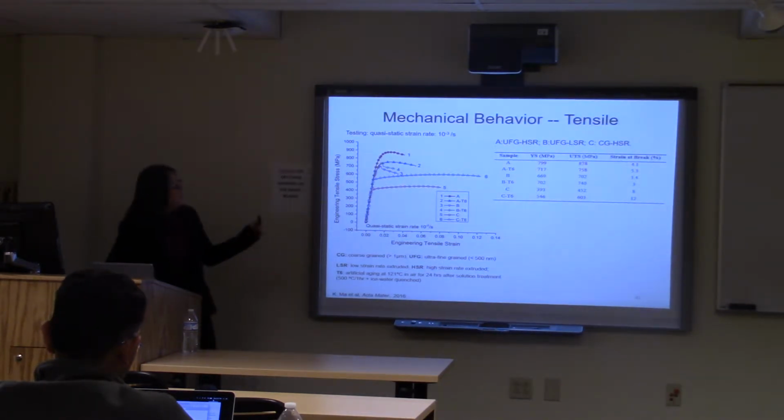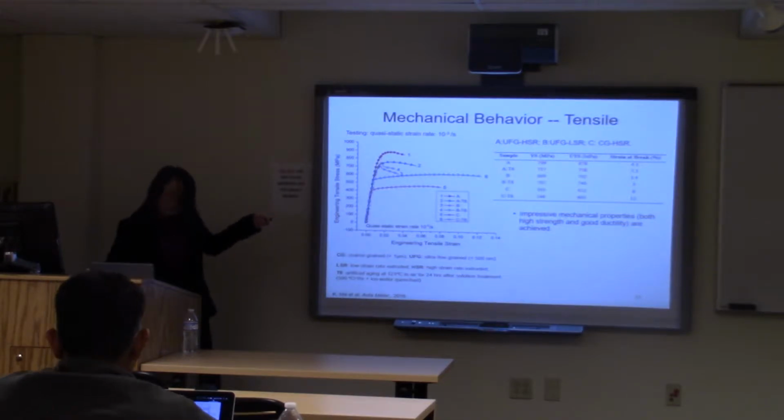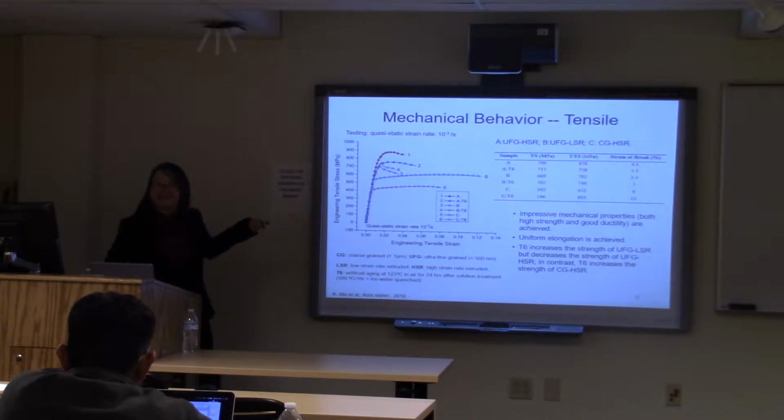And this is what I get. The curve one first, a very impressive improvement, like a little bit of improvement in terms of mechanical properties again. But there's still interesting things going on here. We have the uniform elongations. But if we compare curve 1 to 2, now 1 is the extruded condition, 2 is the T6 temper.